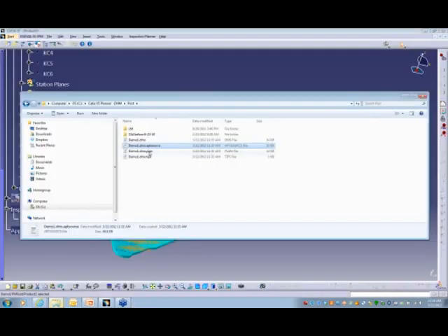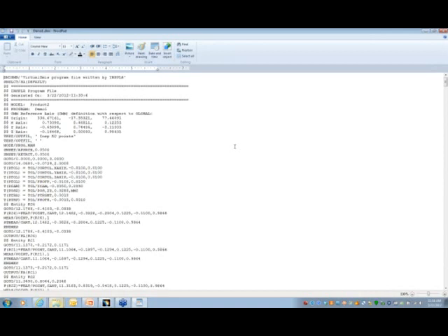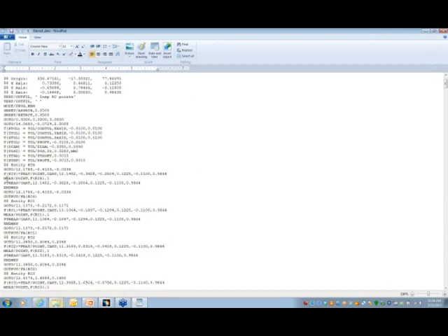And then finally, we create the inspection DMIS plan. So all you CMM guys will understand this. These are the point measurements. It keeps the name in here, the tolerance information that we put early in the program, our approaches and retracts, these outfile statements that go into your report.